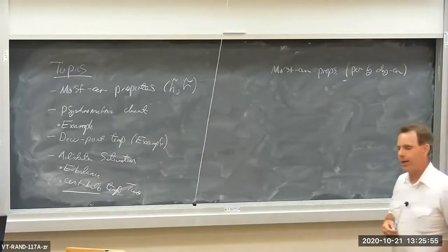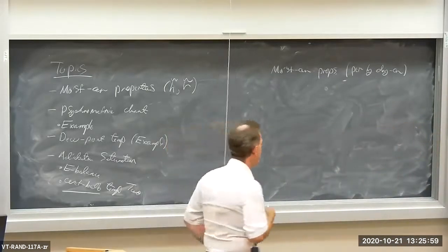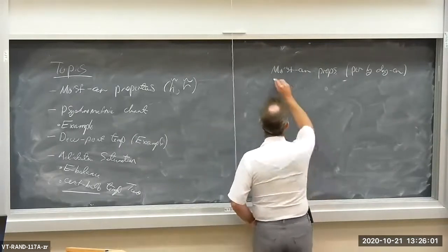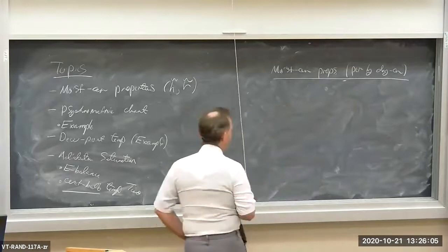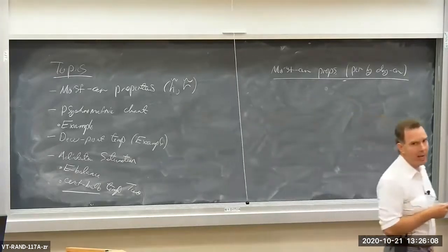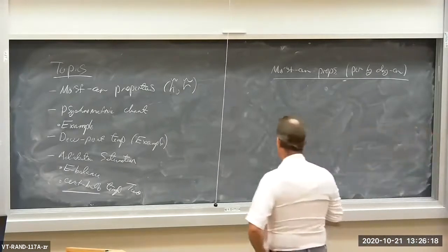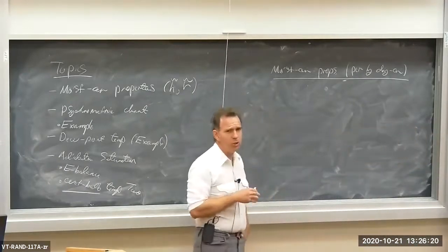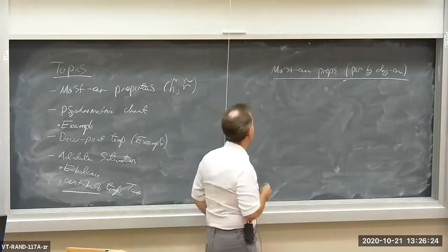Those were all energy per kilogram or cubic meter per kilogram in the case of specific volume. So the way we do these psychrometric problems is we're not dealing with a per kilogram of moist air mixture. We're going to be evaluating and doing all these problems in the future on a per kilogram of dry air basis. If we make it per kilogram of mixture, it's just way too complicated.